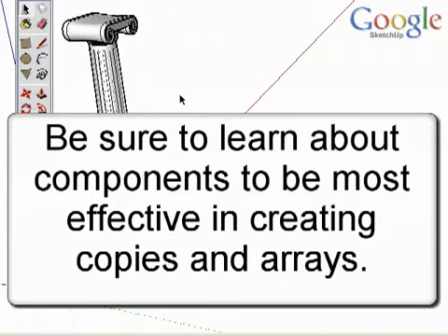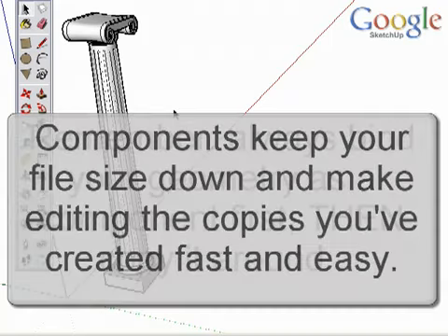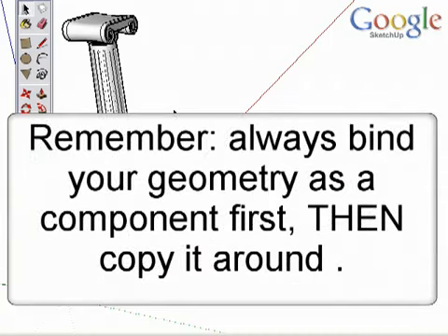And one final tip about copying and arrays. If you don't already know about components in SketchUp, we highly recommend you learn about components and recommend you bind your geometry together into a component before making copies and arrays. It will improve your efficiency and help keep your file size smaller.